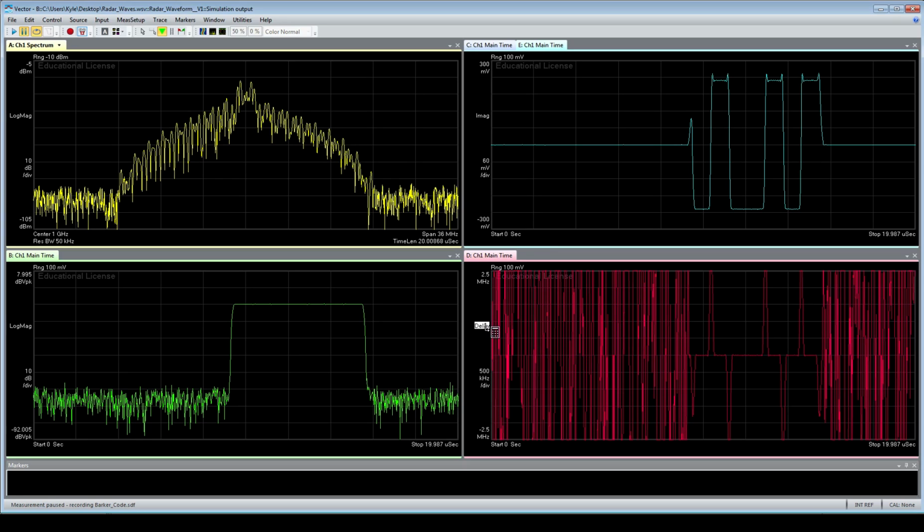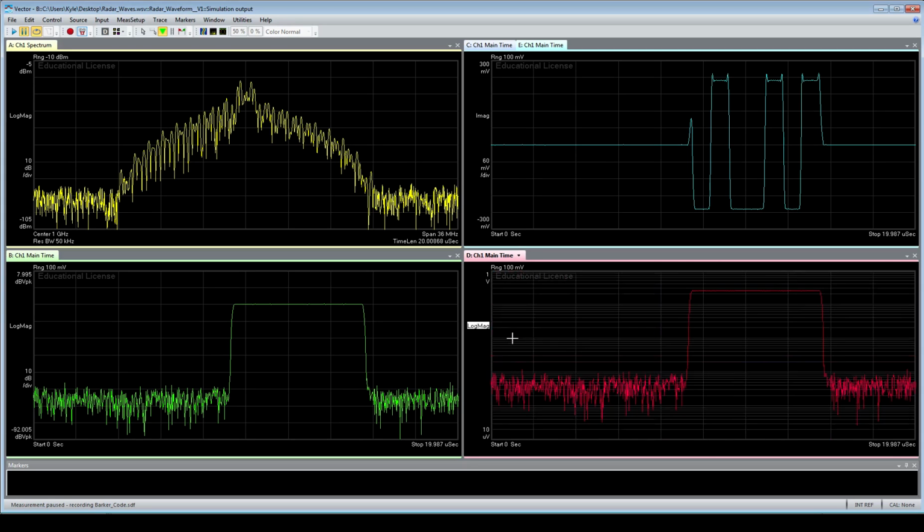For the delay, in this case, we can see that the delay is triggered where we get our bit changes. And Barker codes are a phase shift keying signal. They come in a variety of different numbers of bits, up to 13. If you want to check out any of the books on radar, usually they cover these. They have some unique characteristics because they limit time domain side lobes after you apply a matched filter.